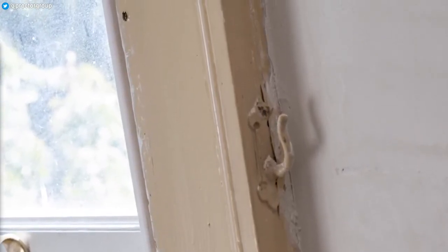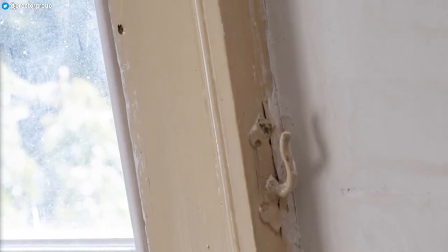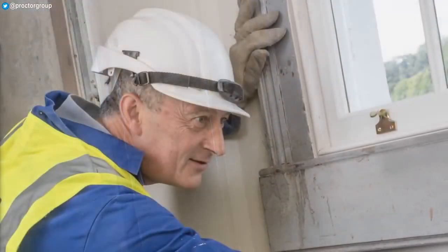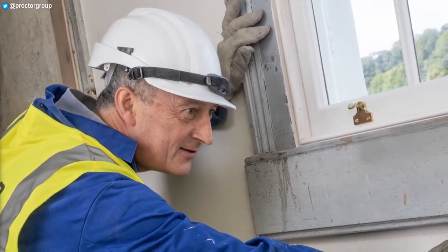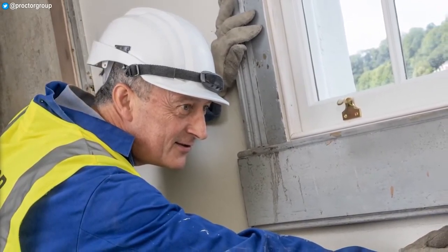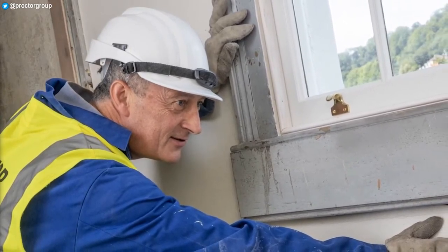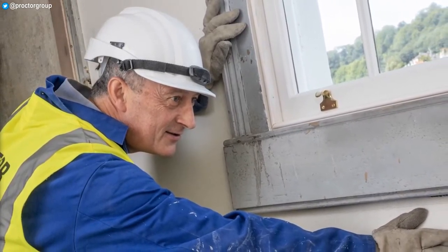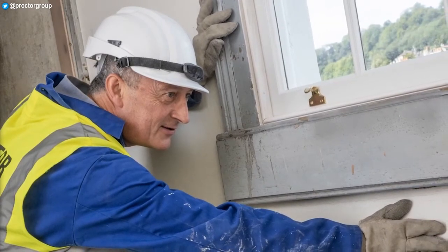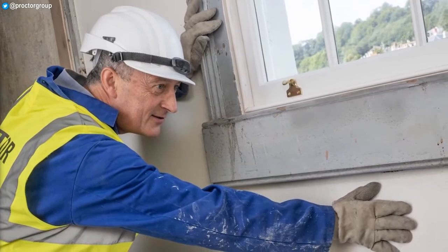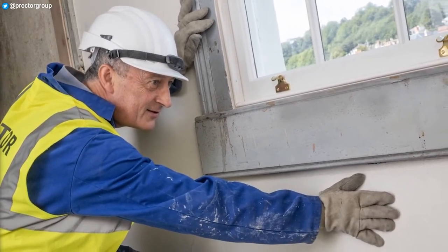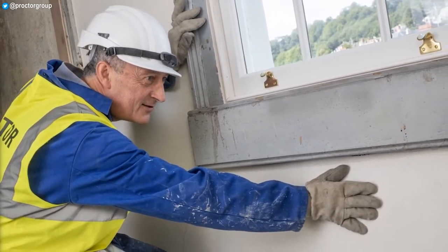Mike's research led to Spacetherm, however, and working with his architect, he was able to reduce this to just 20mm using Spacetherm Multi, reducing the associated disruption while still delivering a meaningful thermal upgrade which was acceptable to both building control and conservation officers. A lime plaster finish was applied professionally by a contractor upon completion of the installation, complementing the permeability of the Spacetherm systems and protecting the original stonework.